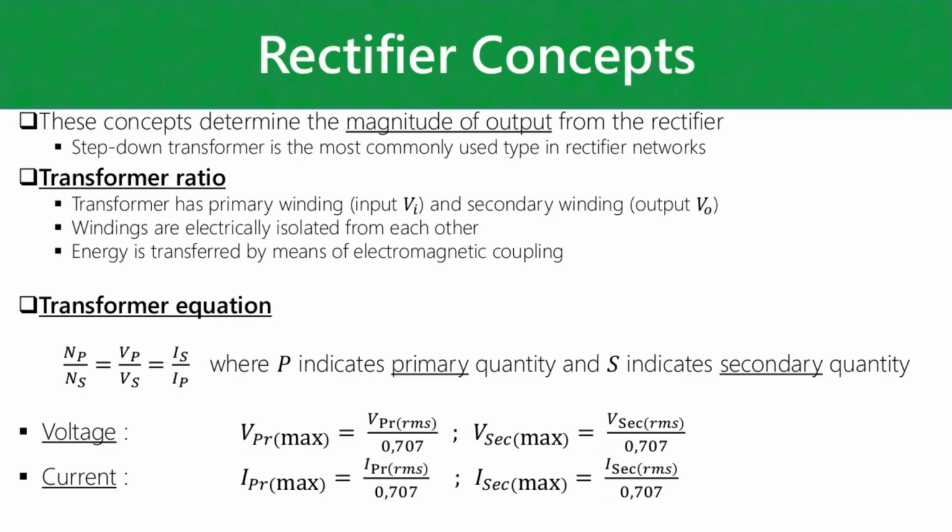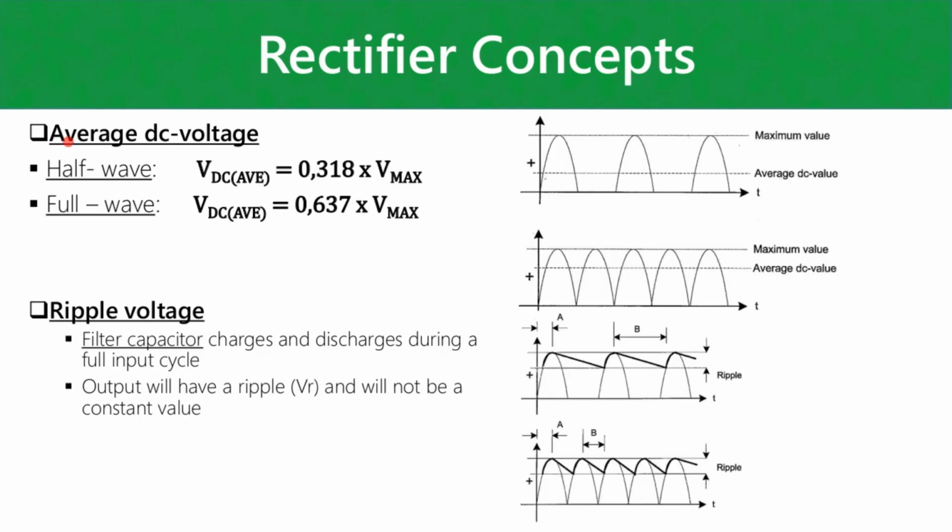If you however add filters to the circuit, that changes things a little bit. You can also have transformers, but transformers are very straightforward to deal with. This is just pretty much N3 and N4 work again. If we take a look at these equations here, I want to warn you guys, because I do see people using these equations sometimes for rectifier circuits that are filtered. These are for unfiltered circuits, right?